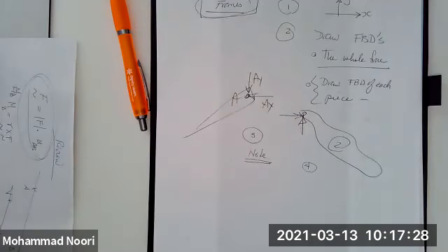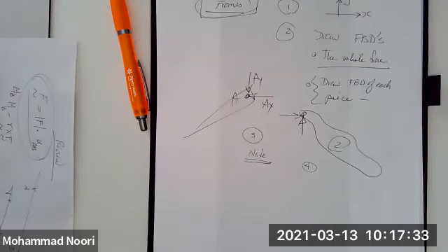You always end up with one free body diagram. You have to always end up with one free body diagram that you have not used, because you always have one plus number of unknowns that you need. So we use that free body diagram that you haven't used to verify the answers. That is, sum of forces along X, sum of forces along Y have to be 0. Okay? So that's in a nutshell overview of frame problems.